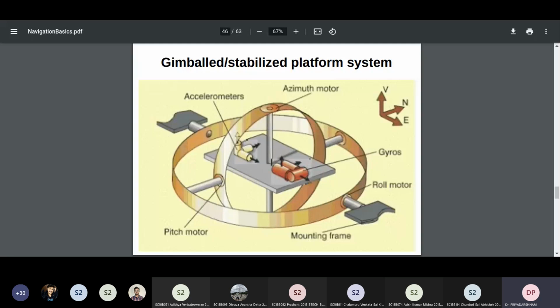These are among the most fundamental difficulties in these inertial sensors. They all have drifts. They don't measure precise values. There are many kinds of drifts. If you switch on and switch off, it will measure different things at different switch-ons. And if you keep it on with the same measuring inputs, the values will also change.